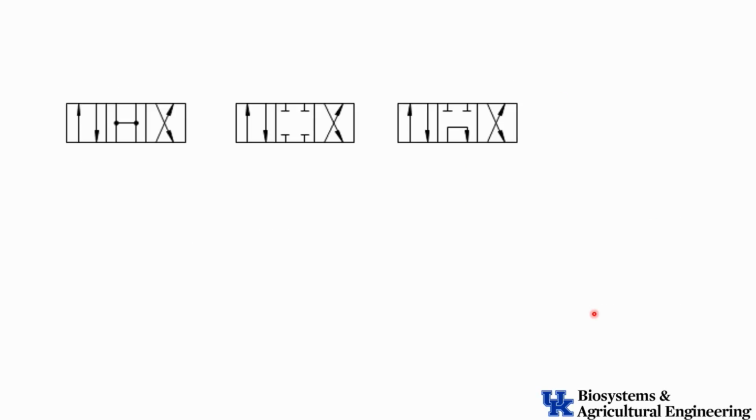So let's look at the JIC symbols for these. Again, they're very, very descriptive. So these are what the JIC symbol would look like. And let me get my pen because what we typically show are the different positions. So as I would put this one in a circuit diagram, I would actually have 4 lines connected to it like this. 2 of these lines, one would be my pump, one would be my tank, and these over here would be my port A and port B. And so that would tell me which way that liquid is flowing, which way I would allow it to flow.